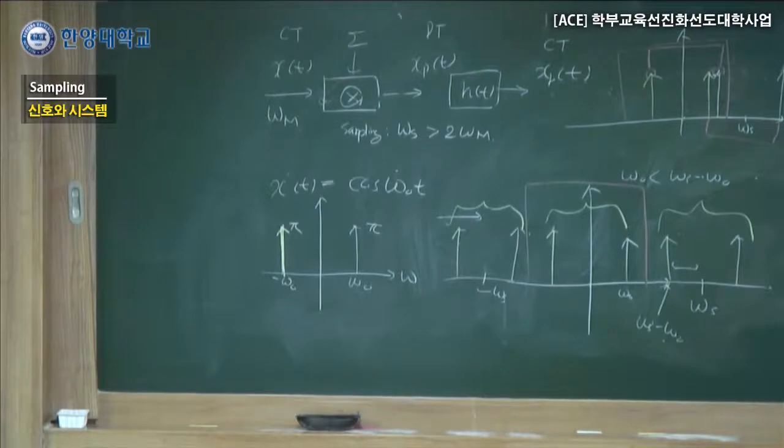In this case, this is our cosine with faster frequency, and then we are picking values, which show up looking like this. If you want to draw a line, can you draw a line? No, it's impossible, because you can go like that, or they may be smaller, they may go like that, because we don't know the data over here. We know the data in between, but in this case we don't know the data over here, or over here. So it's very hard to find how it looks. This example briefly shows you what happens if aliasing happens.